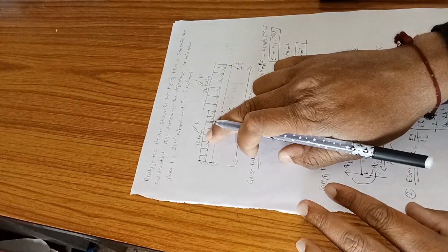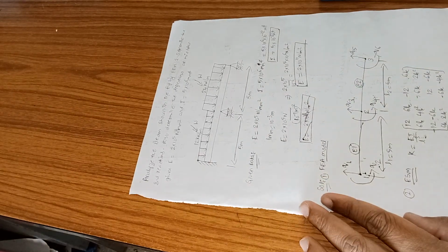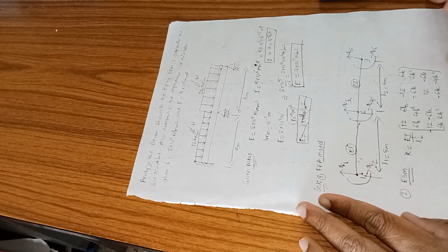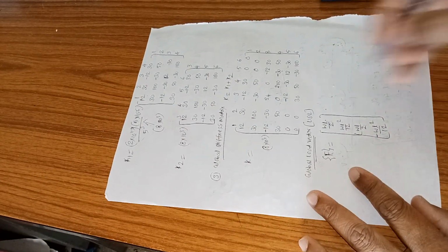So for element 1, the W value is going to be 12. I'm not going to just write it as 12, but 12 into 10 to the power of 3. The reason is it's going to be converted from kilonewtons to newtons. Then the L value is going to be 5 for both the elements. So for element 1,